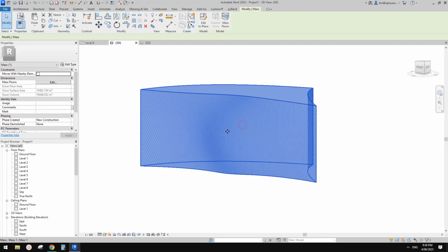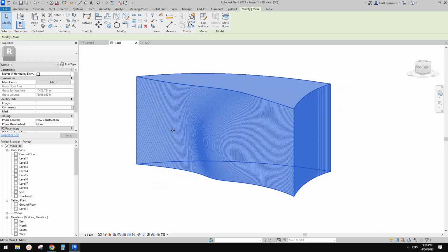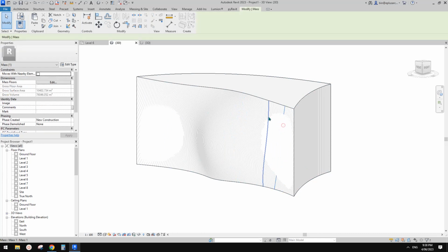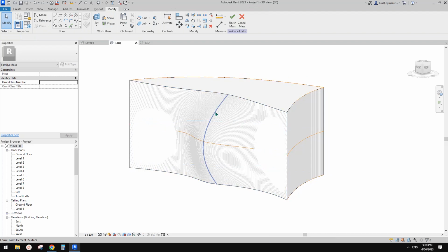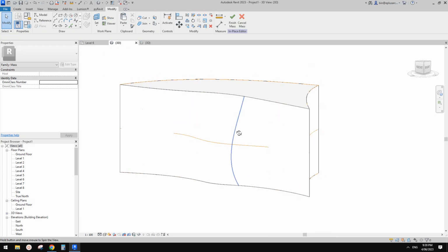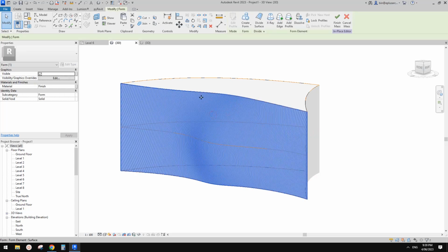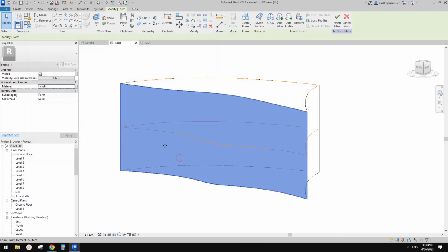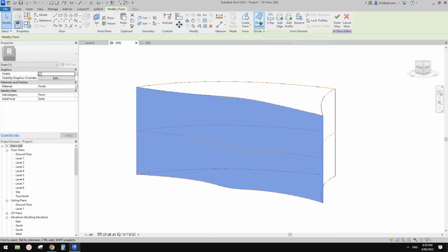Select this, and let me just tab. Oh, hang on. Sorry, you need to go into the modeling place and then tab. Maybe we should turn off the material pattern because it's annoying. Let's go here and turn this off. Okay, so now if you tab, you can select this surface and use default surface.